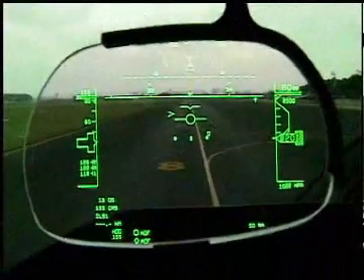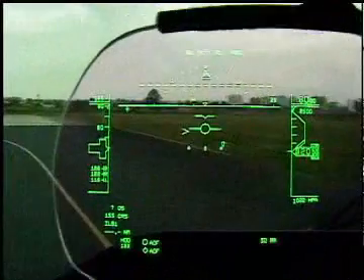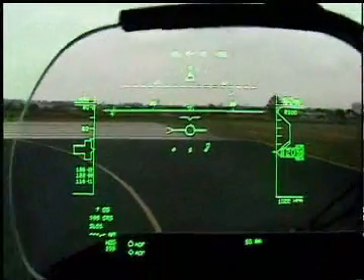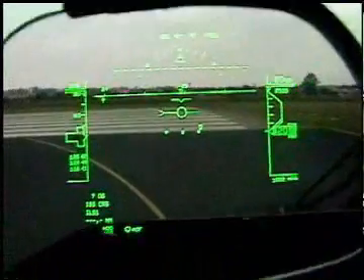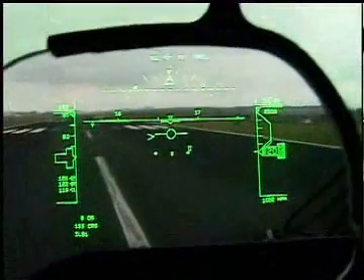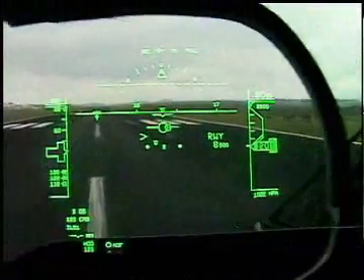For a low visibility takeoff, the general operating procedure is to taxi the aircraft into takeoff position over the runway centerline. The selected course is adjusted as necessary to overlay the selected course symbol on the actual runway centerline at the furthest point of visibility.